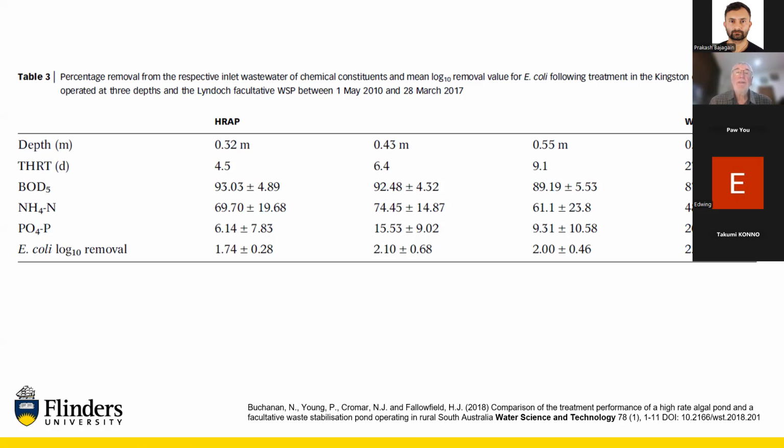Yeah, that's all I'm after, really. You'd expect that if you increase the depth under the same conditions, you're going to get less algal production, because the light climate within the culture, the light being intercepted by the algae, scattering, all the geometry of the vessel changes in terms of light availability for the algae. So this is an experiment to see if you do that for wastewater treatment, and you're relying on algae for wastewater treatment, by changing the depth, do you change the outcome of the treatment? Does it really change the treatment?